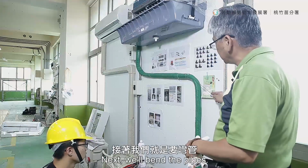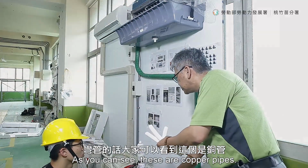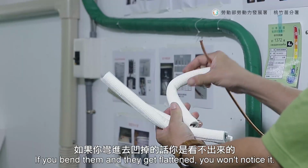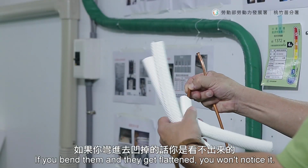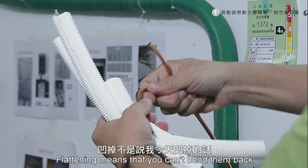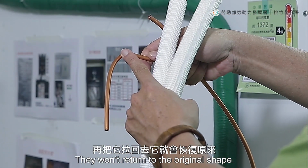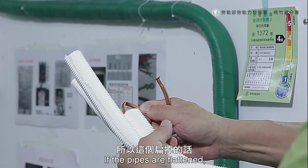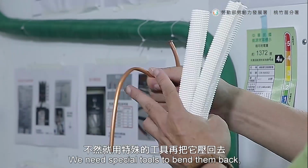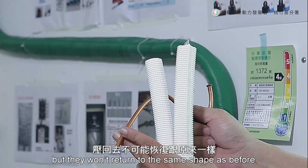Next, we'll bend the pipes. As you can see, these are copper pipes. If you bend them and they get flattened, you want to notice it. So sometimes they're already flattened. Flatten means you can't bend them back. They won't return to the original shape. If the pipes are flattened, it could be a problem. We need special tools to bend them back, but they won't return to the same shape as before.